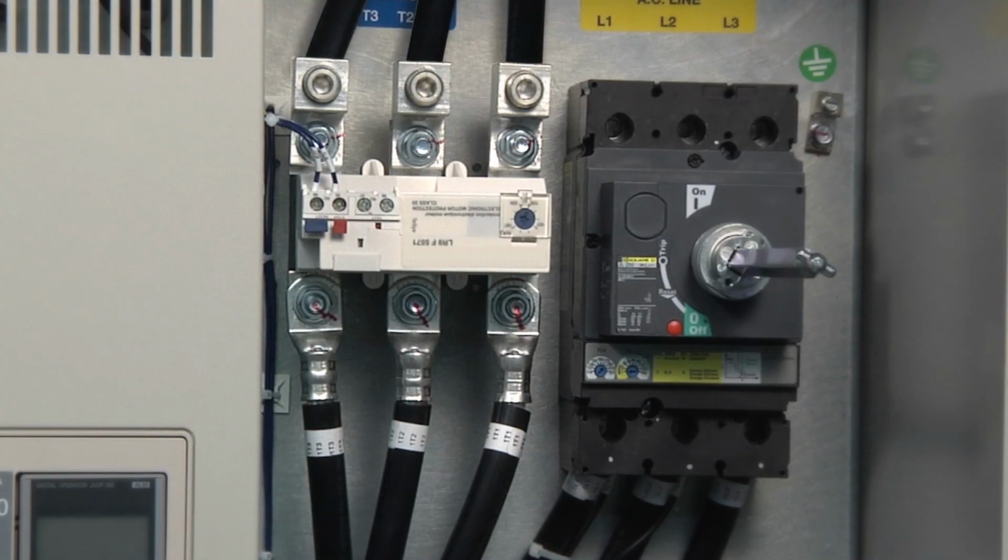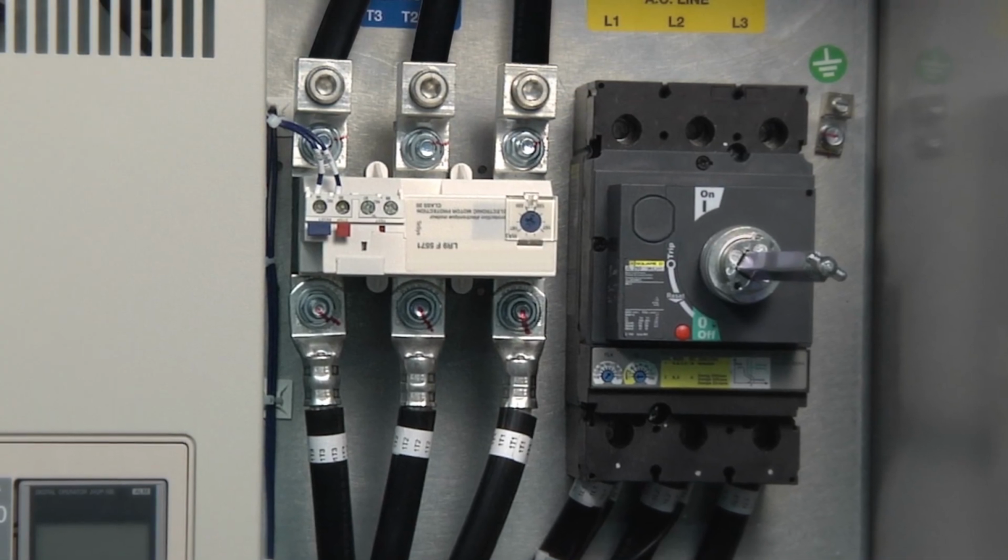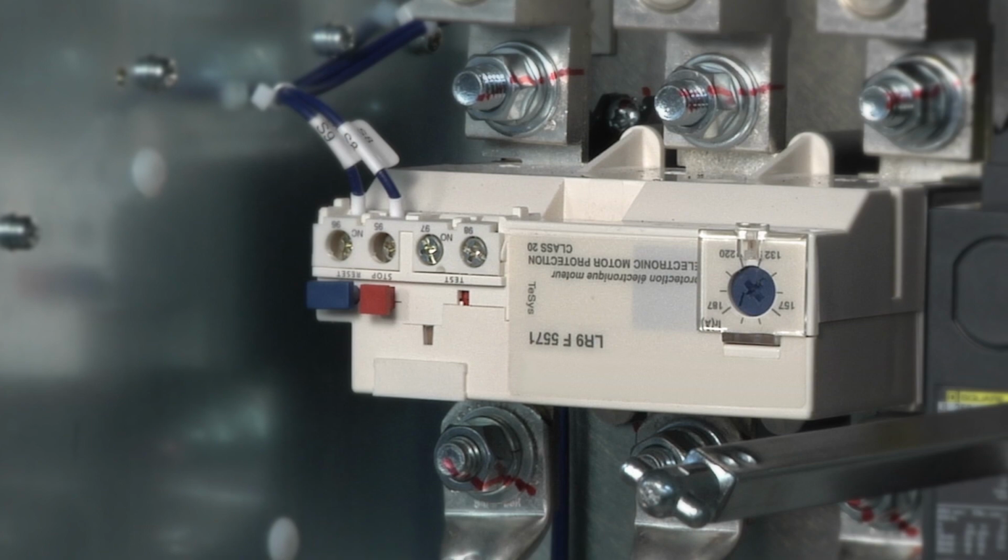When the motor slips beyond its breakdown torque, it begins to produce less torque, which then causes the motor speed to decrease even more and in many cases stall. This situation usually results in damage to the motor if left in this state due to overheating of the stator. Though typically there's an overload relay that will protect the motor from damage.